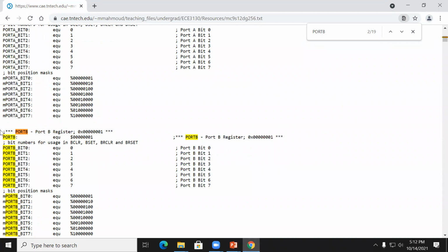Yeah, look here. Port B, the address is number 1. This is how the address is, number 1. Okay, guys? Okay, conclusion. Again, if I want to use any port, there are 2 registers I have to use. One register is the data direction register, as I explained before.